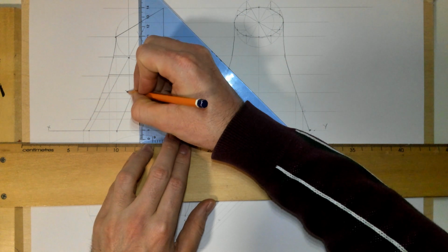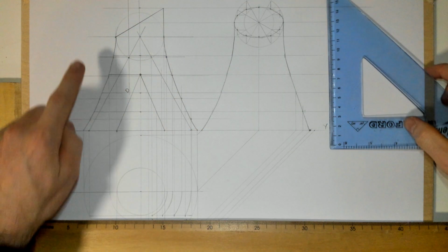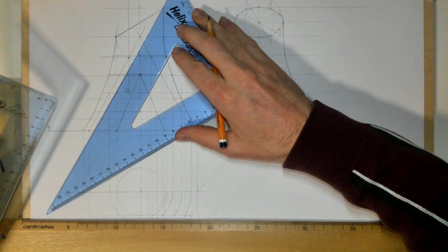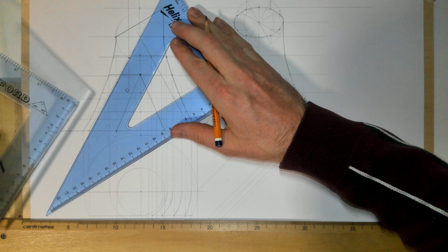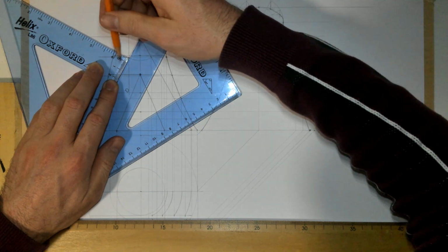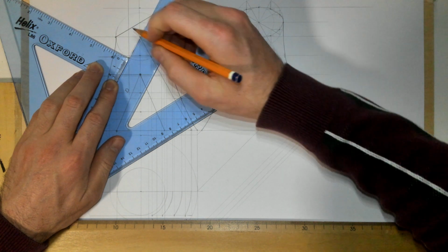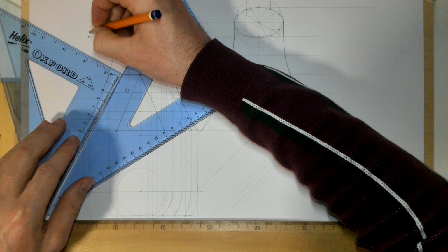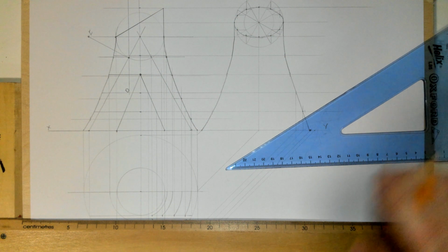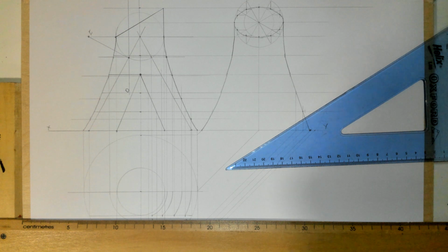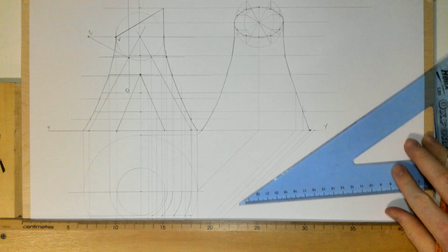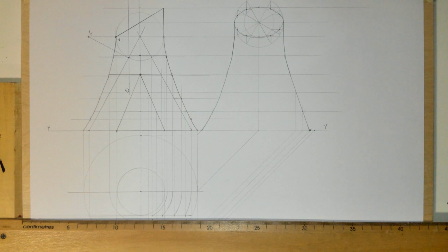Label it D and D for that hyperbola. And to get the focal point, you go perpendicular from the asymptote to where it hits that circle that we've drawn in. So perpendicular there, that gets F on that line, and now you find the focal point and the directrix. Determine the positions of the focal point and directrix for the branch. You're not asked for the vertex. If you were, that would be the vertex there as well. Okay, and that's your full question complete.